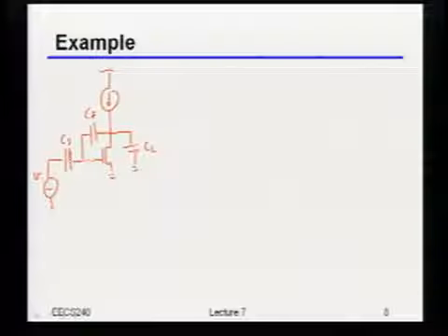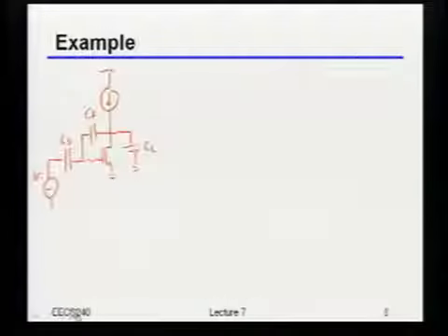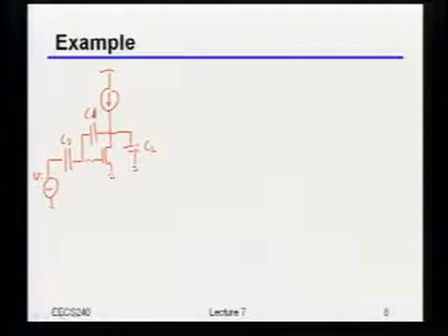Because we're doing the feedback through capacitors rather than through resistors, the gain, rather than being R2 over R1, as it is over here, is going to be CS over CF. Just because, with capacitors, the impedance is like 1 over the capacitance. So now what I want to do is go through and figure out what's the effective noise at the output from this amplifier right here.